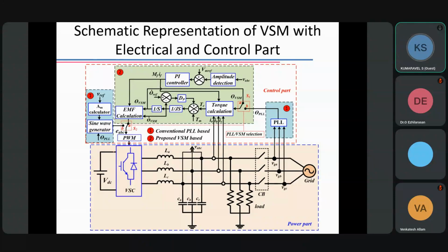Also, you have a capacitor bank in the DC bus, so you can control the reactive power also. So you can either control P, active power, plus or minus. Also, you can control this reactive power plus or minus. If you draw a curve, something like this,